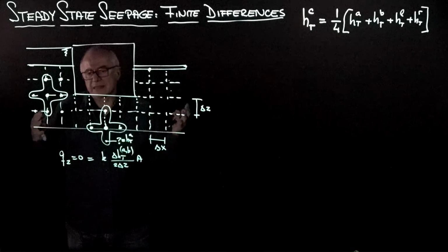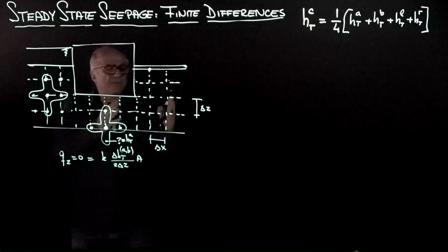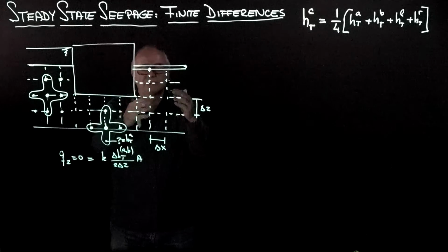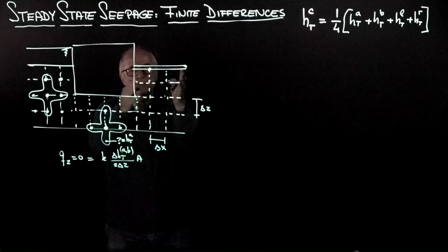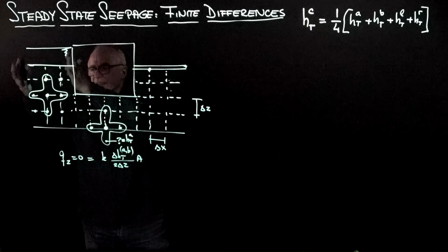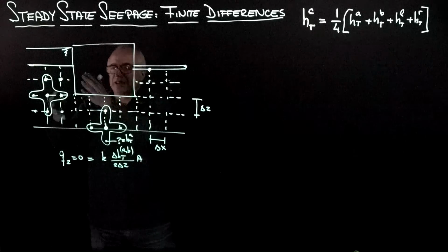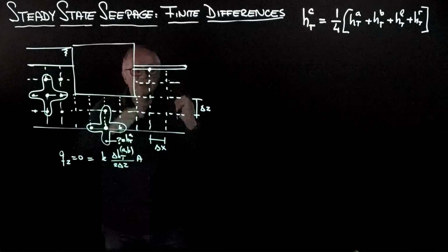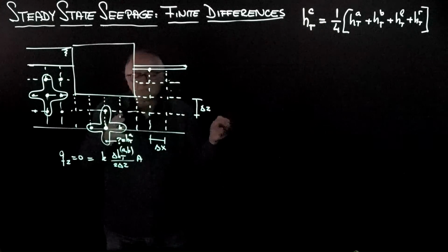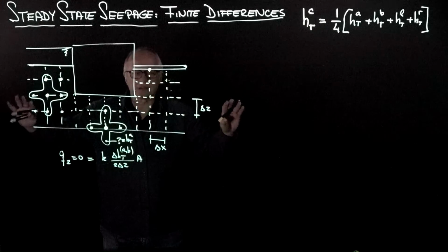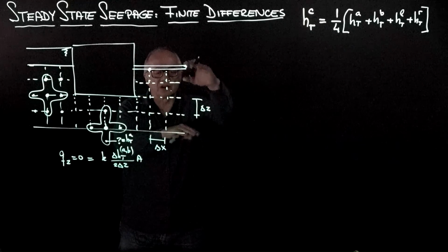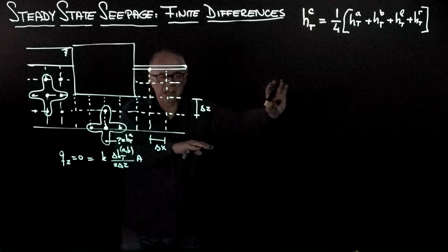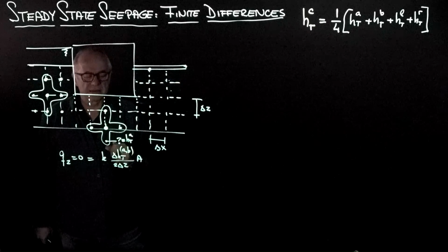And that is always an important question, and probably if you remember when you draw the flow net, most of the flow is going to come from the near field. There is a funnel that comes from the near field of the barrier and goes nearby, but just to make sure that you don't have boundary effects, you may want to go 2 or 3 times the height of the pervious layer away on each side.